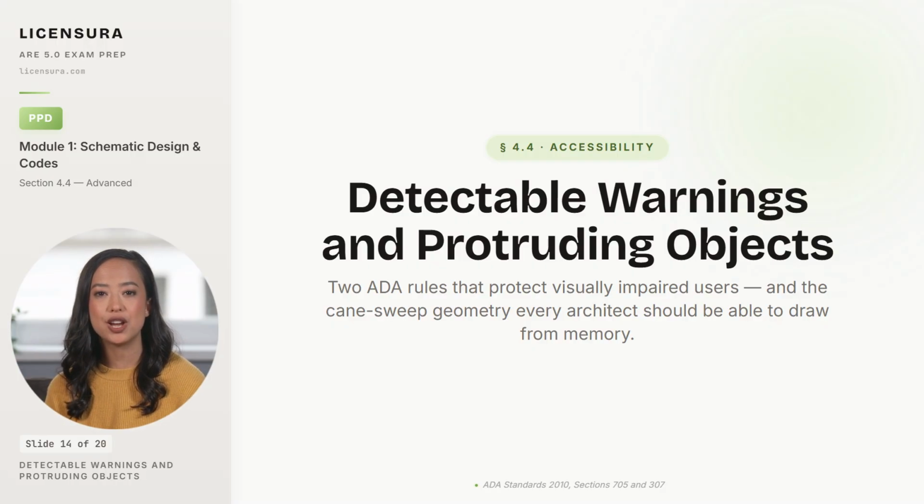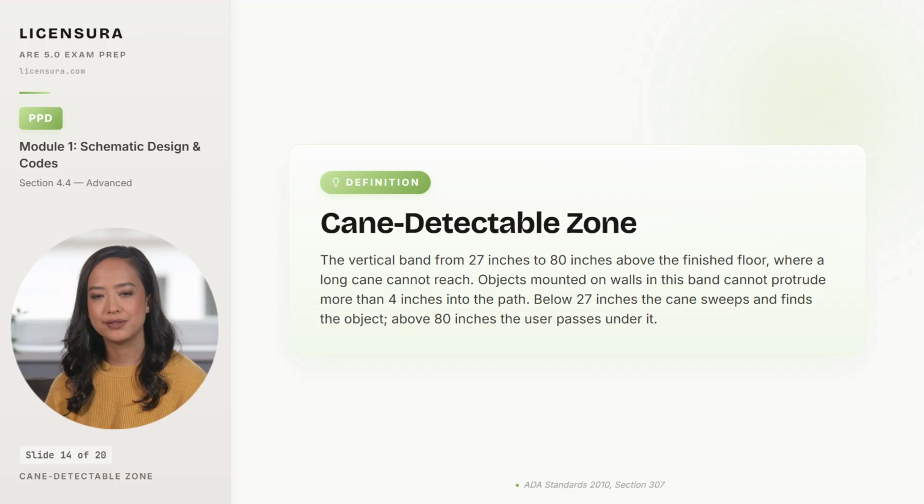The cane detectable zone is worth a formal definition before the location rules. The cane detectable zone is the vertical band on every wall between 27 inches above the finished floor and 80 inches above the finished floor. And the ADA protects that band specifically because a long cane cannot reach into it. The cane sweeps the floor in an arc roughly 4 inches above the surface, so anything mounted below 27 inches gets struck by the cane before the user's body reaches it. Anything mounted above 80 inches passes over the user's head with clearance.